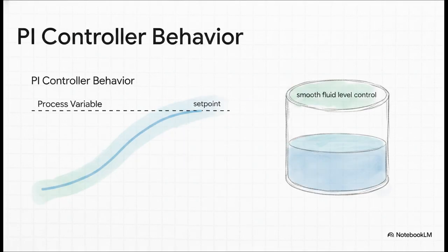The reaction curve for this PI controller is just fantastic for accuracy. Okay, yes, it rises a bit more slowly than a pure P controller. It kind of takes its time, but it completely eliminates that steady-state error. It hits the set point precisely, right on the money.